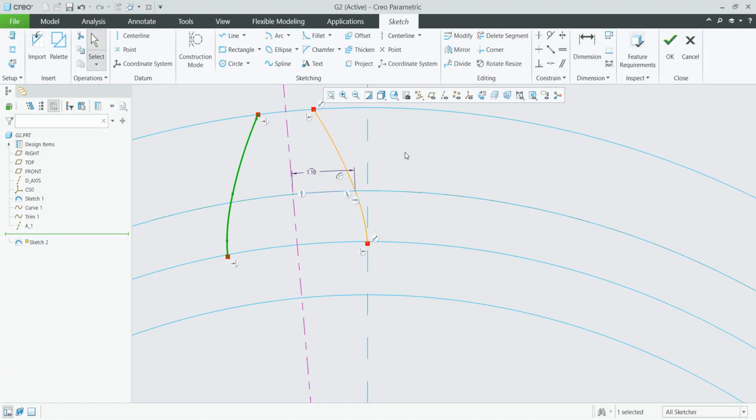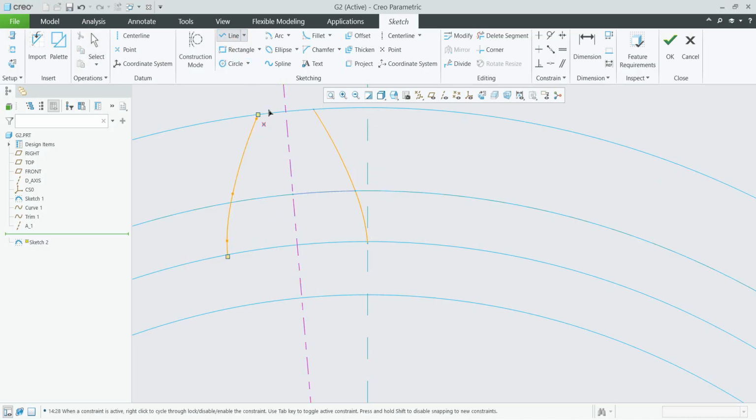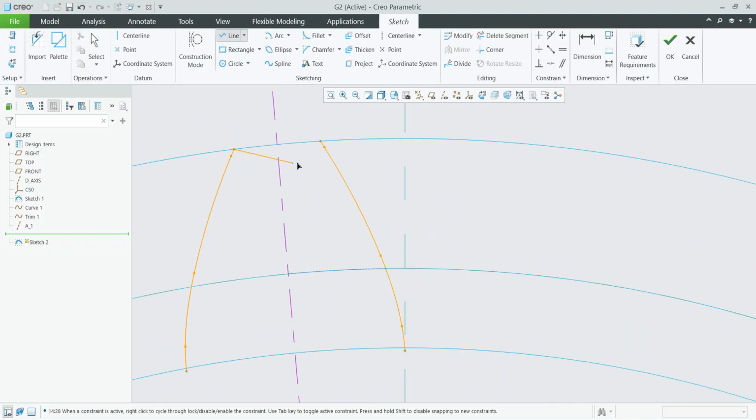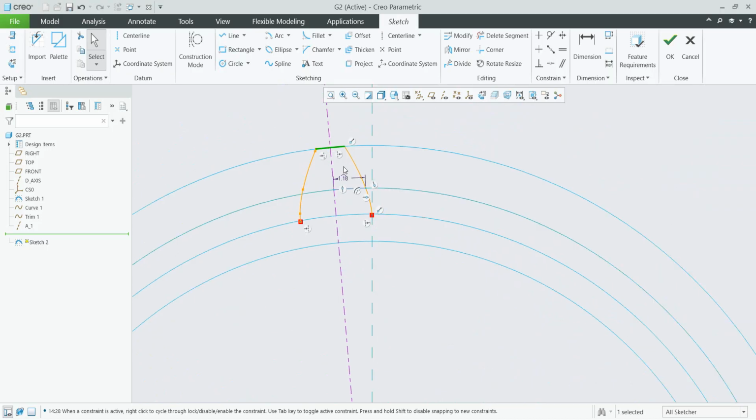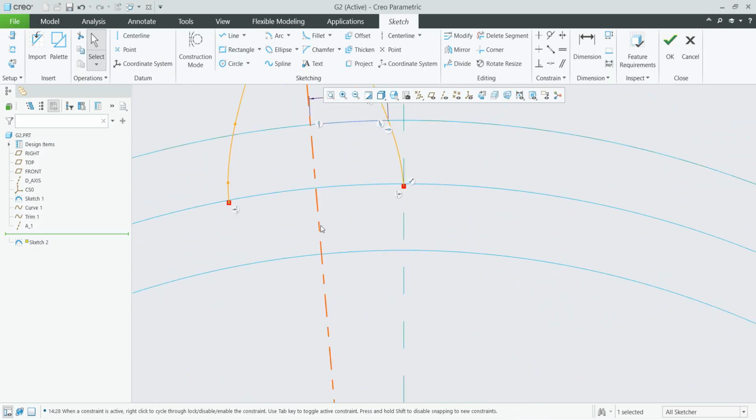So what does it mean? We have specified the necessary shape, and the thickness of the tooth defined on the pitch diameter is set based on the relations again. What we would like to do, you are able to project the top line, or you can simplify the shape and only use a straight line here. And also over here on the bottom, you are able to create your custom shape.